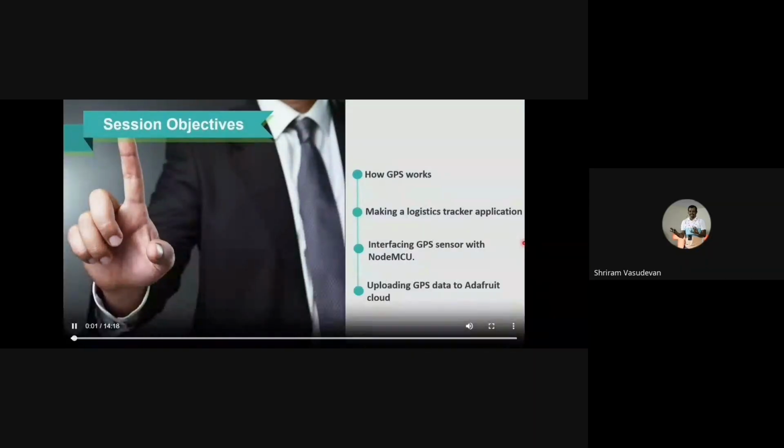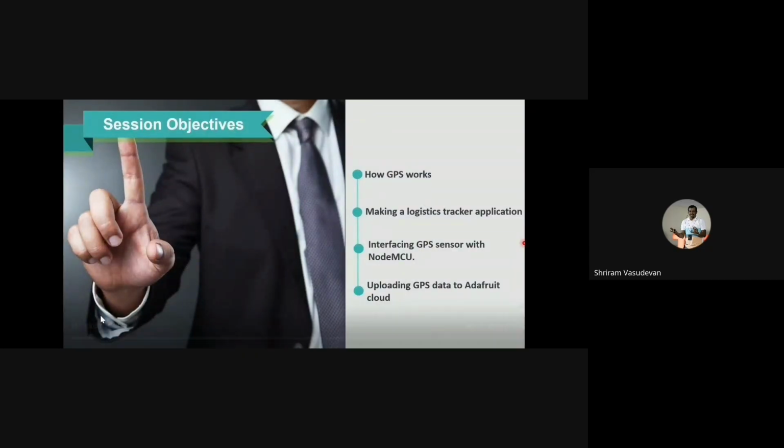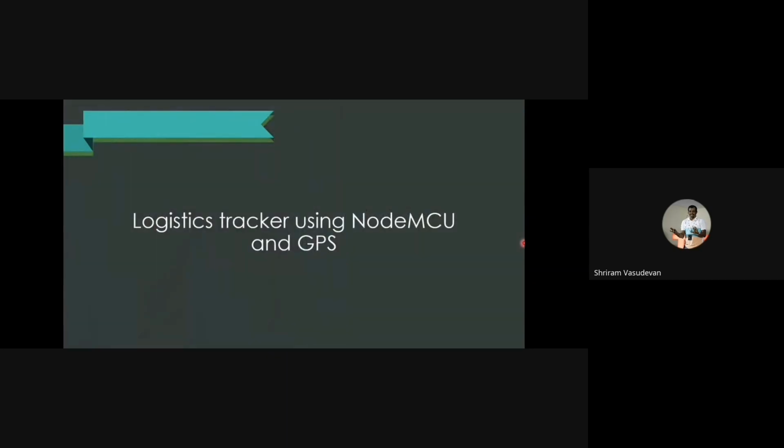In this session, you will get a clear understanding about how GPS works, how we make a logistics tracker application, interfacing a GPS sensor with NodeMCU, and uploading the GPS data to the Adafruit cloud. Logistics tracker using NodeMCU and GPS.